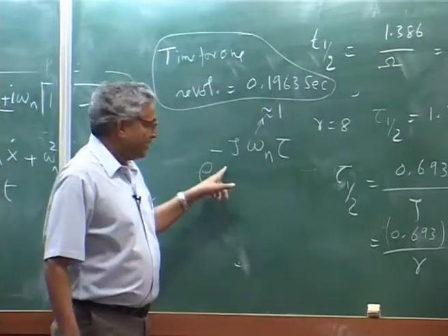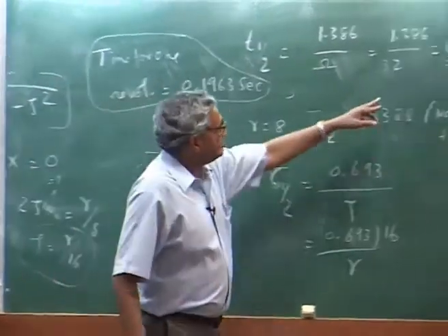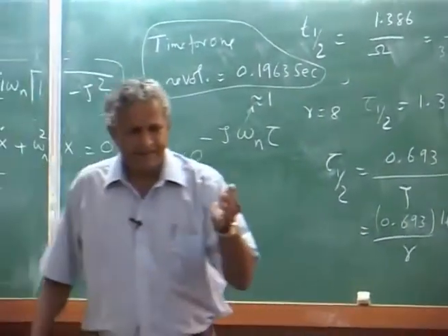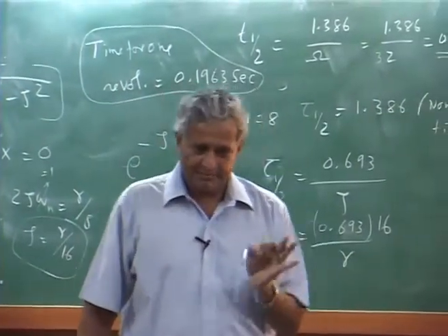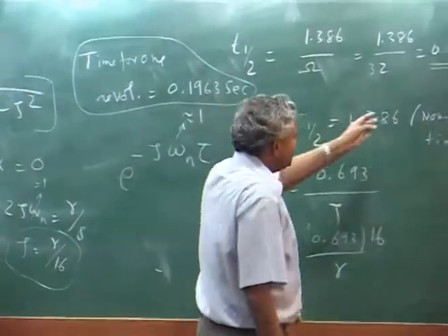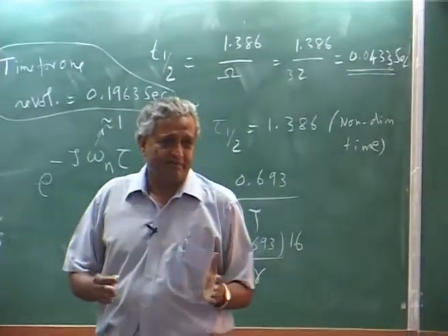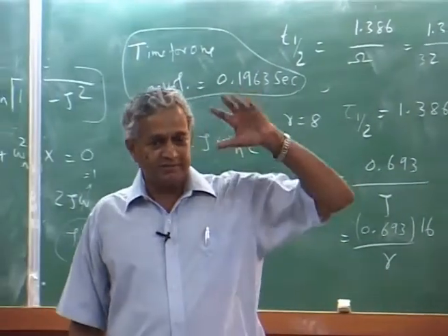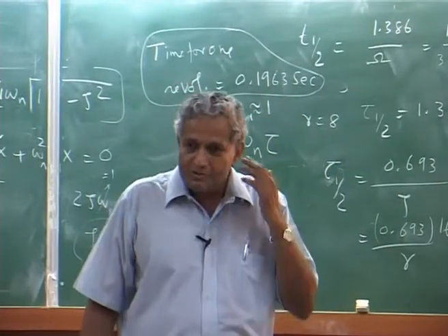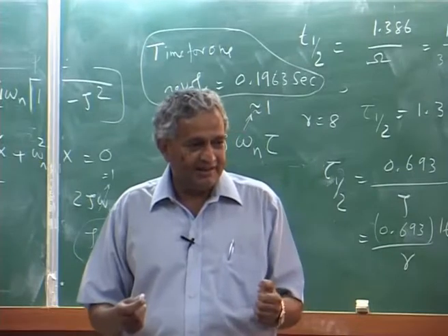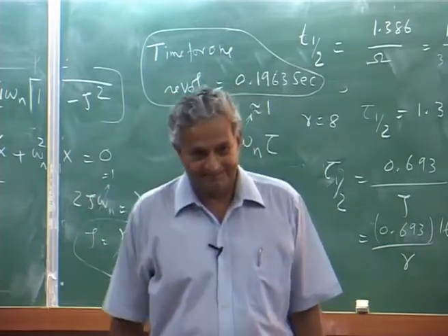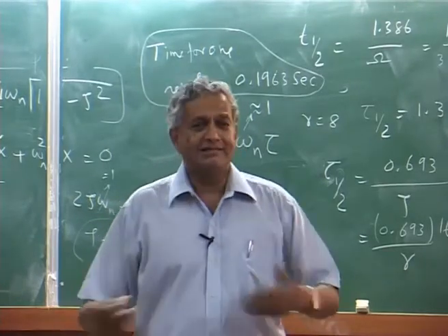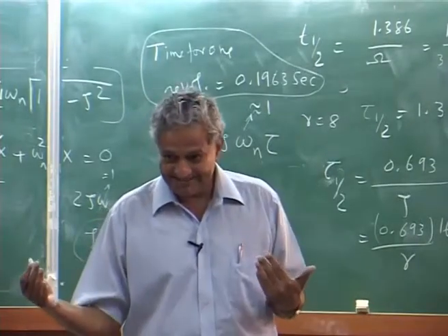So for the blade to go around once, it takes around 0.2 seconds, whereas the amplitude decay happens in 0.04, which means the time constant is really very small; in the sense it quickly reaches its value. That is why when the pilot gives any input, the response of the flap is quick. He won't recognize or feel a delay in the response of the blade.